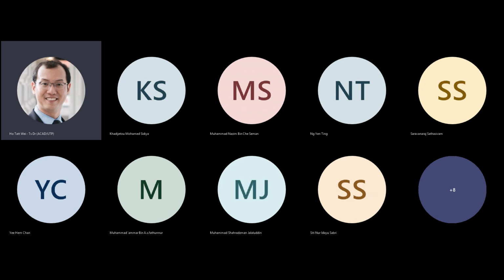Now, of course, this is a very canonical, straightforward, simple to understand way of building multiplexers. There are actually faster multiplexers than this, and that would be the example of what we call pass transistors or pass gates. And the way you can think about pass gates is something like this.